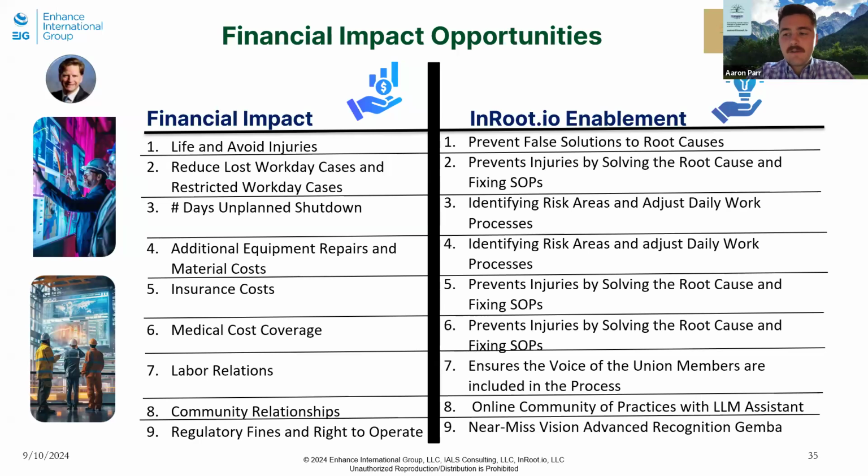Yeah. Aaron? Yes, and similar to that, I won't talk about any one specific RCA, but on one of the teams I had worked with previously, we got into this iteration of doing an RCA, whether it was quality or safety, and all of the equipment issues we had found and dug into, we used that data to essentially guide our predictive maintenance program that we were developing. In any predictive maintenance program, one of the first things they recommend is, let's look at temperature and vibration, and we'll put it on all your pumps. Well, we had more pumps than we wanted to put sensors on, and there were other types of equipment we were more concerned with and more critical to our operations. So what we had uncovered in those RCAs was essentially the starting point for what equipment we included in our predictive maintenance program first.